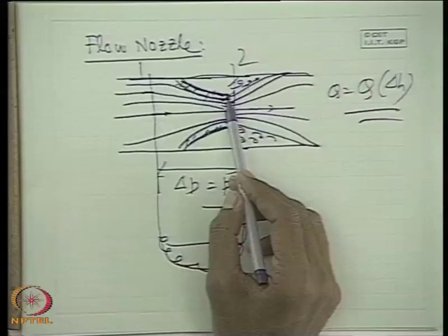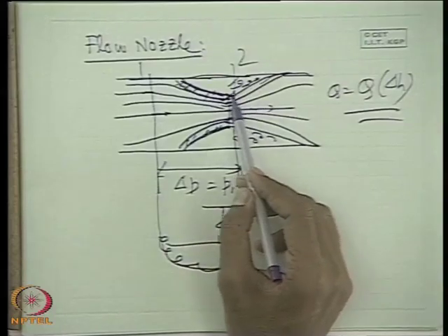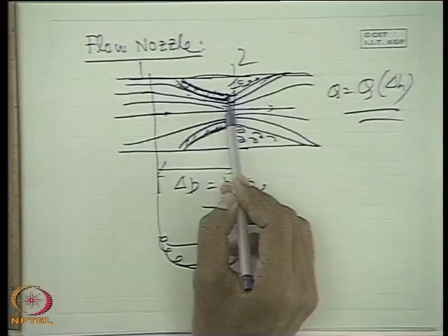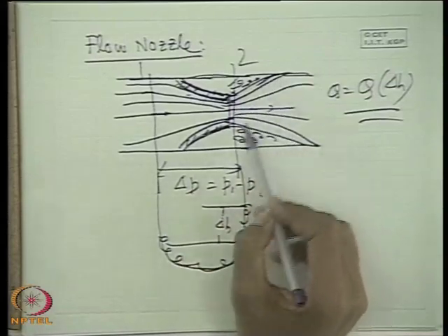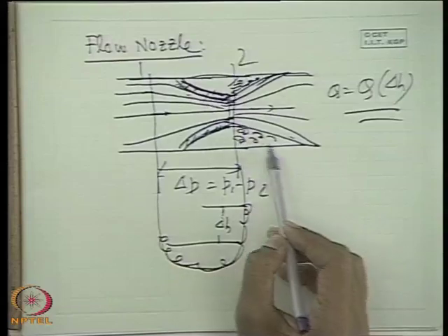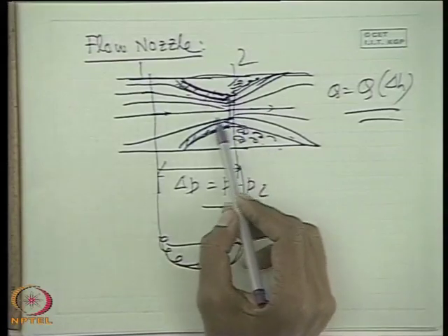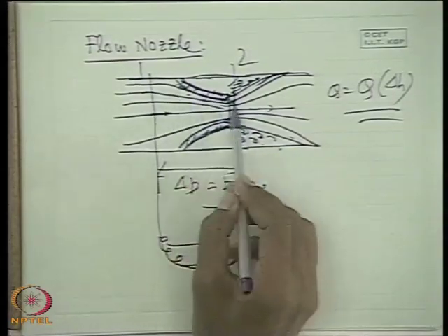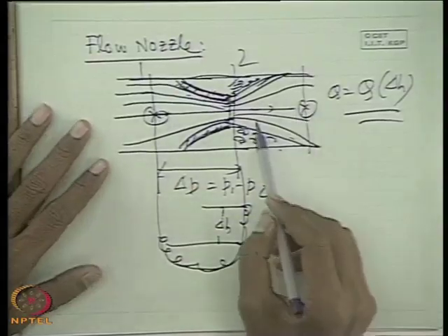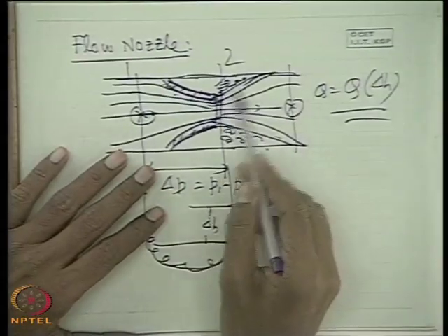But here in the flow nozzle, the losses are more than for the venturimeter. Why? Because in this section there is no divergent part. So the fluid stream, after converging smoothly along the surface, diverges like this, so that the formation of eddies takes place due to separation losses. Therefore the total energy loss will be more. But this is counterweighed by its lower cost.